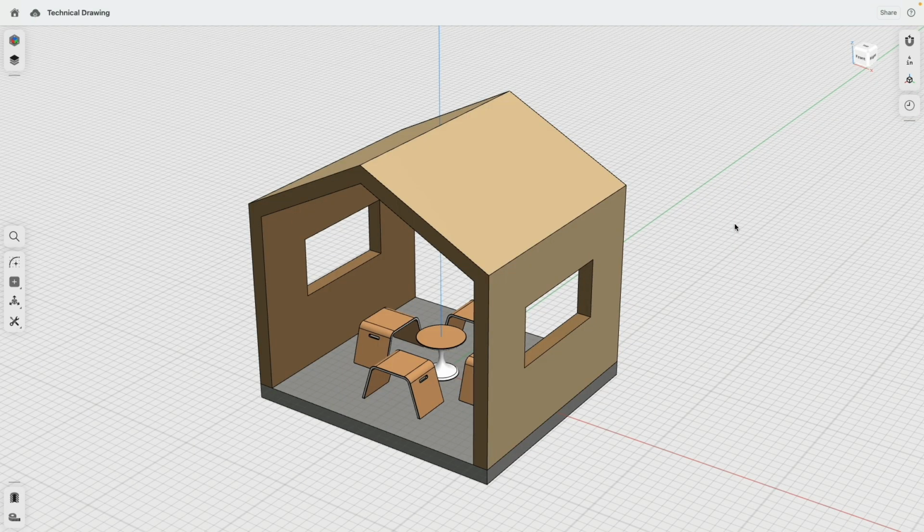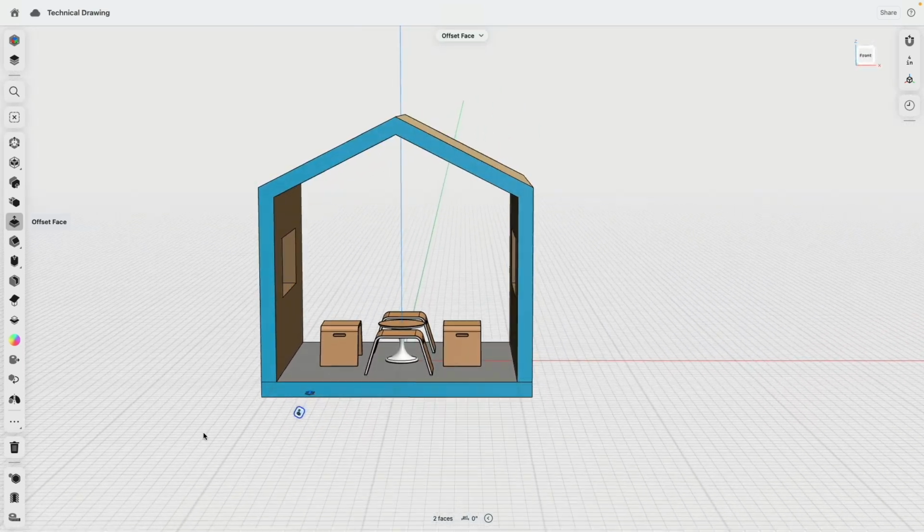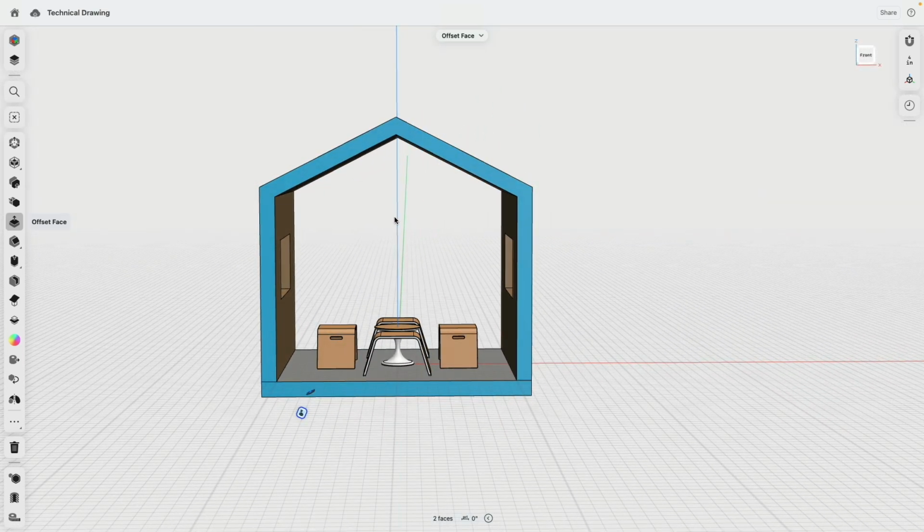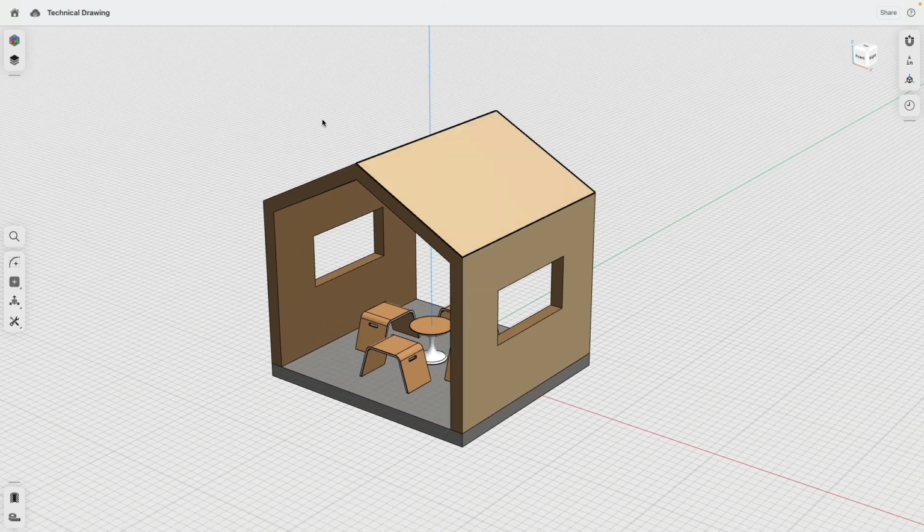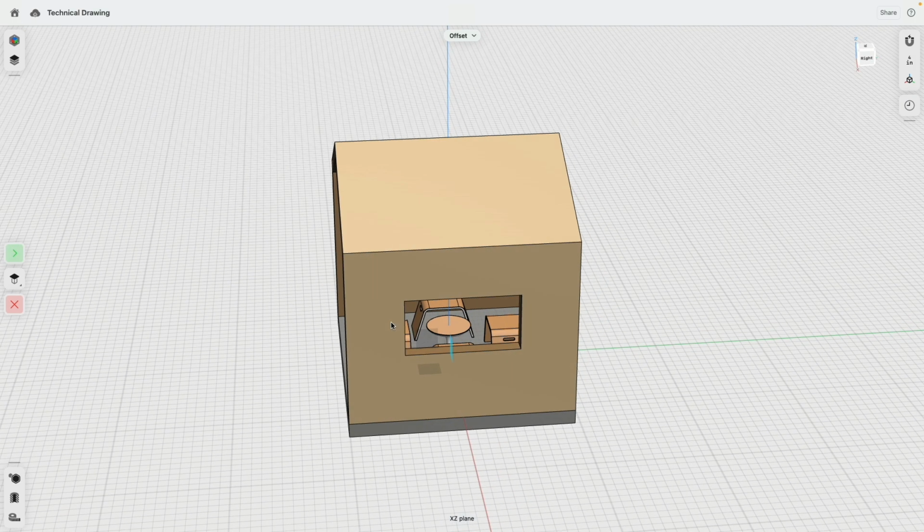Let's do it. Let me begin by showing you how easy it is to create to-scale projection drawings of your objects inside your design scene. That basically means I, for example, want these faces which I have selected be projected along this view onto a sheet of paper in the background. Okay, so to do this, we go to add construction plane, select this plane here and bring this over 150 inches. So there's a nice distance.